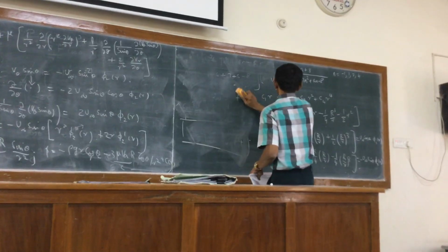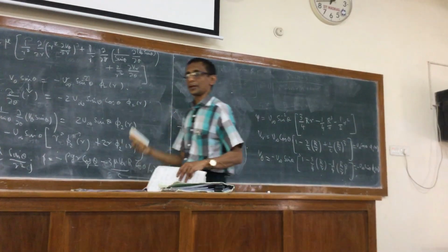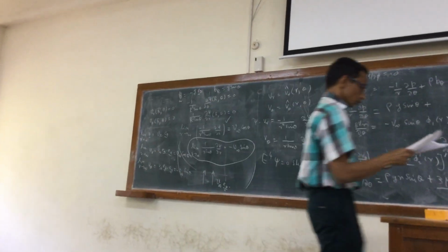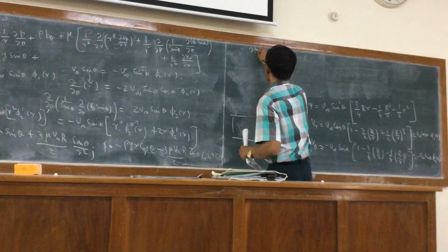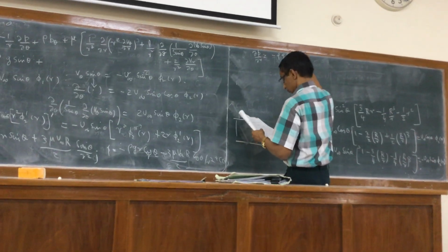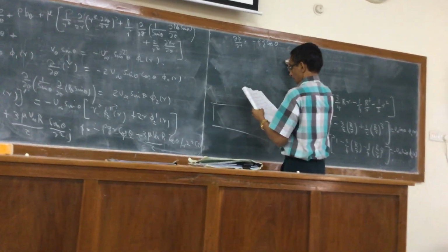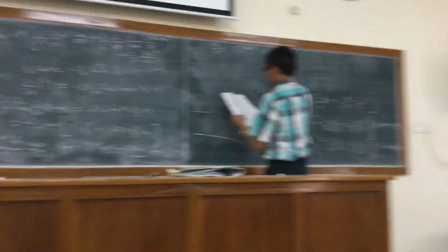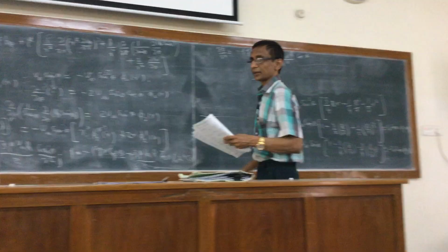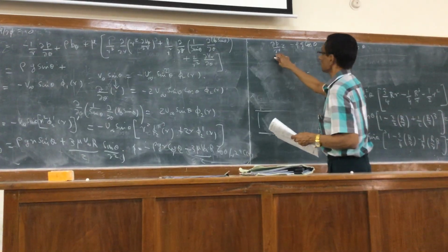for that we have to go to the equation in the r direction and do the same procedure, right? Again, a very complicated and tedious procedure would lead to dp by dr is equal to minus rho g cos theta plus 3. Of course, I can combine that. I'm just writing it as it is in my note. Cos theta can be easily combined. And so dp by dr is given by this.